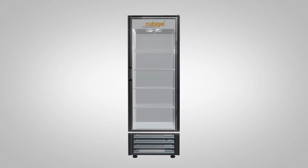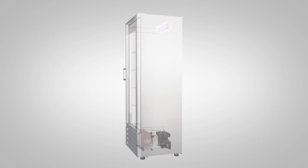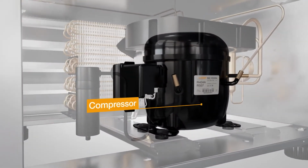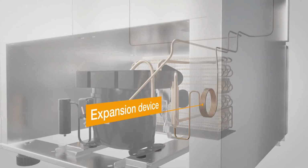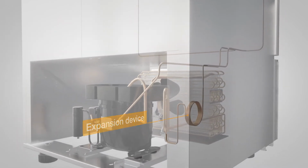To convert a commercial refrigeration system that uses HFC refrigerant to propane, as well as change the refrigerant charge, we must replace the compressor, filter dryer, and expansion device, which can be an expansion valve suitable for the R290, or in our case, a capillary tube.